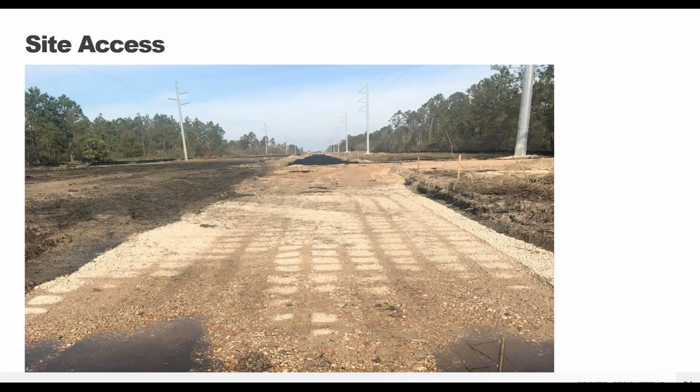Once the panels are completely filled in, you can see both wheeled and tracked equipment can drive over this system quite easily, even when that infill material is low quality. In this case, there's some sand mixed in. Normally it would be horrible to try and drive tracked equipment over sand. There's just no support for those tracks. But with the GeoWeb system, because everything's confined, you don't have to worry about that. You can keep going. You can have this be the access road for any type of maintenance equipment that you might need.